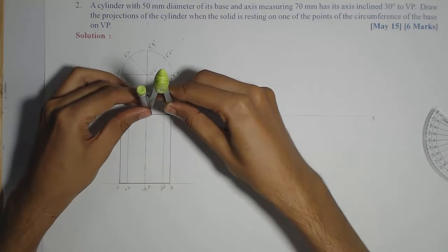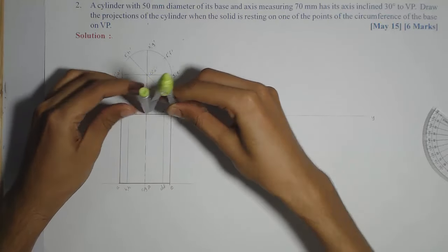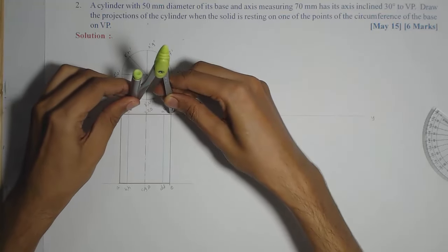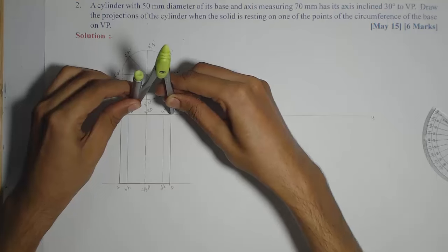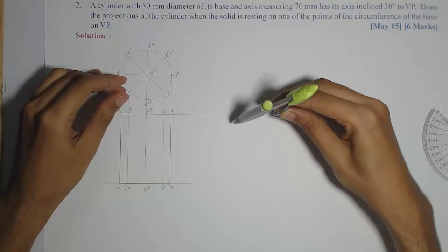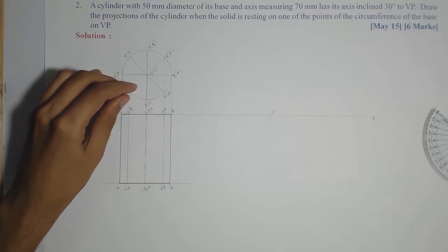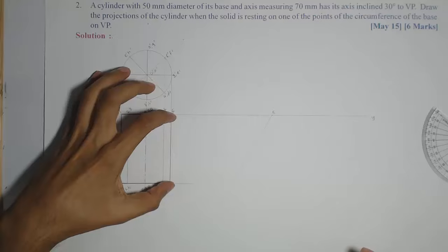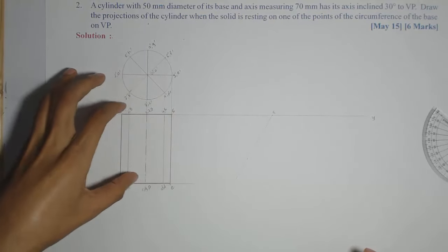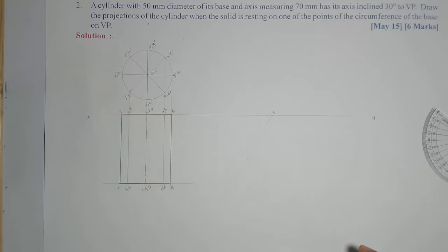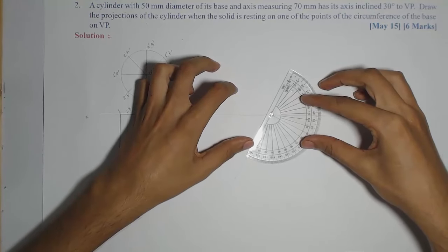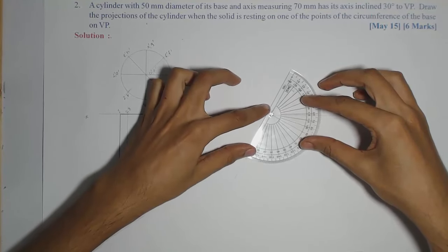Then the center line 3, 7, 4. Add one more division, which is 2 and 8. Now from this base I can draw these two boundaries which are perpendicular to the base. Also 4, 6, 2, 8 and 3, 7 are also perpendicular. So I'll first mark one perpendicular line from 5, and then I'll draw the parallel lines to that perpendicular to mark the other lines.